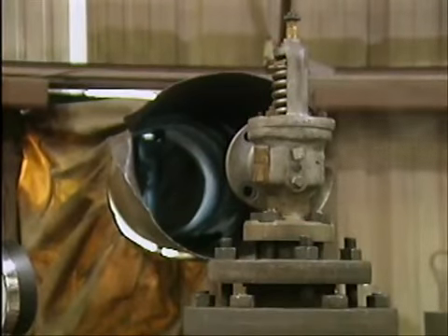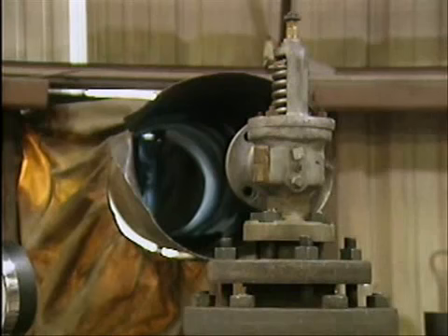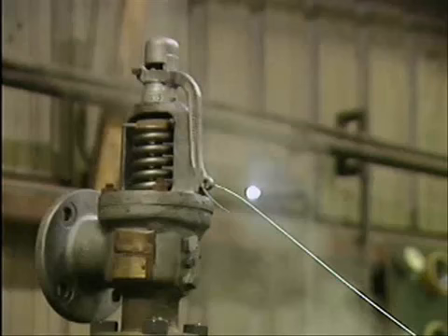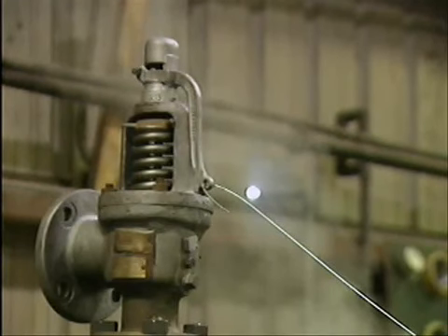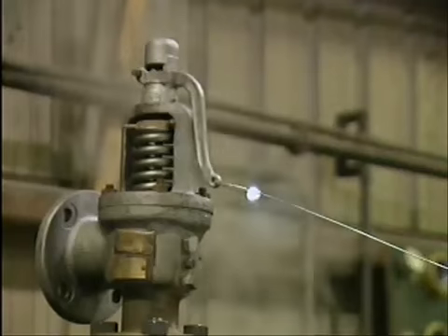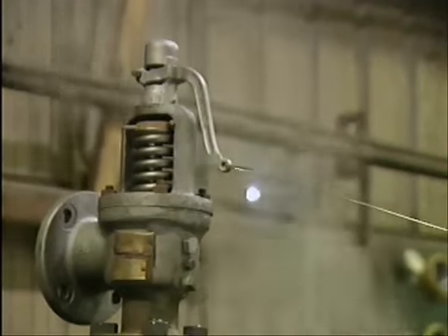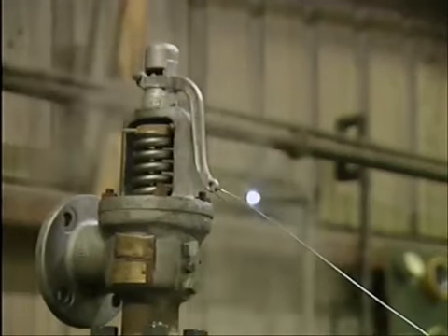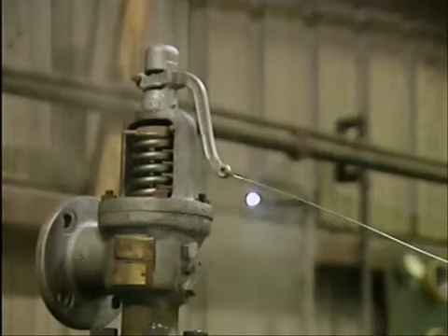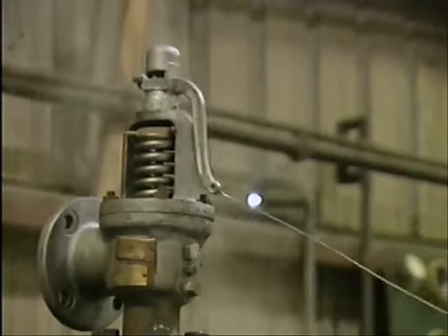Likewise, before hand lifting a valve, you must take appropriate personal safety precautions. Attaching a hook to the valve's release lever enables you to position yourself as far away from the valve as possible. This is important because when you hand lift the valve, a great deal of hot, pressurized fluid could be released. To lift the valve, pull the hook hard enough to open the valve all the way. You should hold the valve open for only 2 or 3 seconds. If you hold it open any longer, the disc could be damaged by the rush of steam.